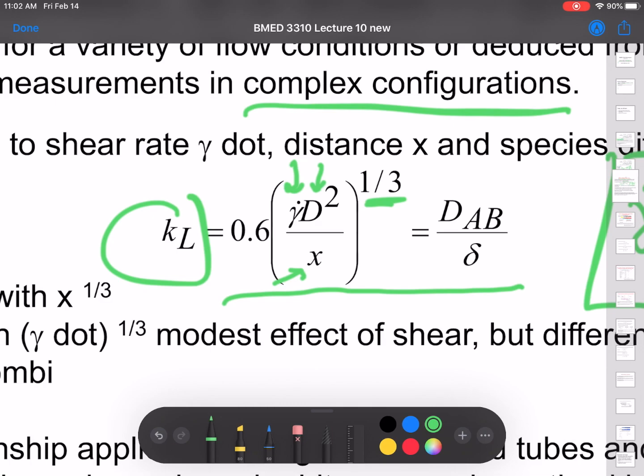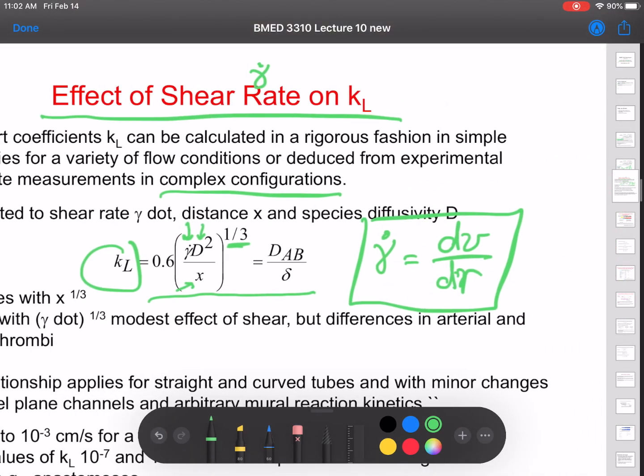We were talking just before we started filming about how shear rate may be a new concept to some of you. Shear is just like plates sliding past each other. Do you have a way to conceptualize physically what shear rate is? I have my hands together, rubbing them together here. So this is the velocity in the x direction, and there's a gradient in the perpendicular direction, which makes it shear.